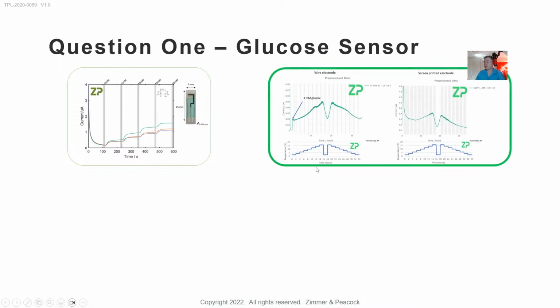I'm also going to link to this as well, where we're actually testing a glucose sensor in glucose. This is 3 millimolar, and you look at that drift, and the drift is actually following a temperature profile. So we're changing the temperature and watching the glucose signal change accordingly. So I can see here quite a strong glucose response. So I would say yes, we tend